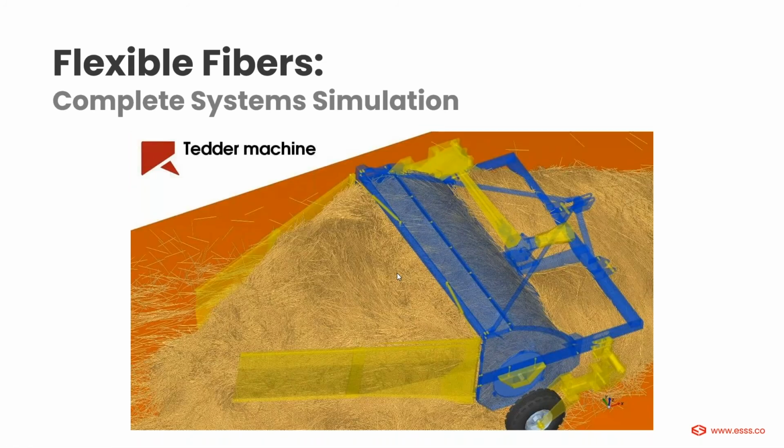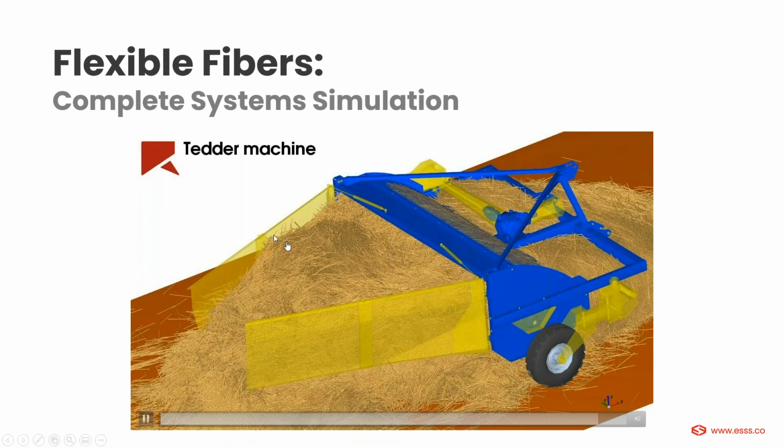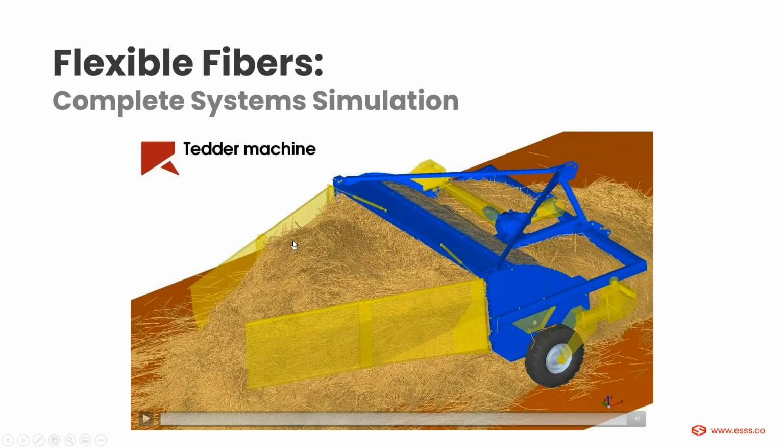Imagine, for these large aspect ratio particles, how many spheres would you require to model such a particle? In Rocky, we have a completely different way of modeling such particles, and the multi-GPU capacity allows you to run this huge amount of particles here, which would probably take way longer to run on a standard CPU-based machine.